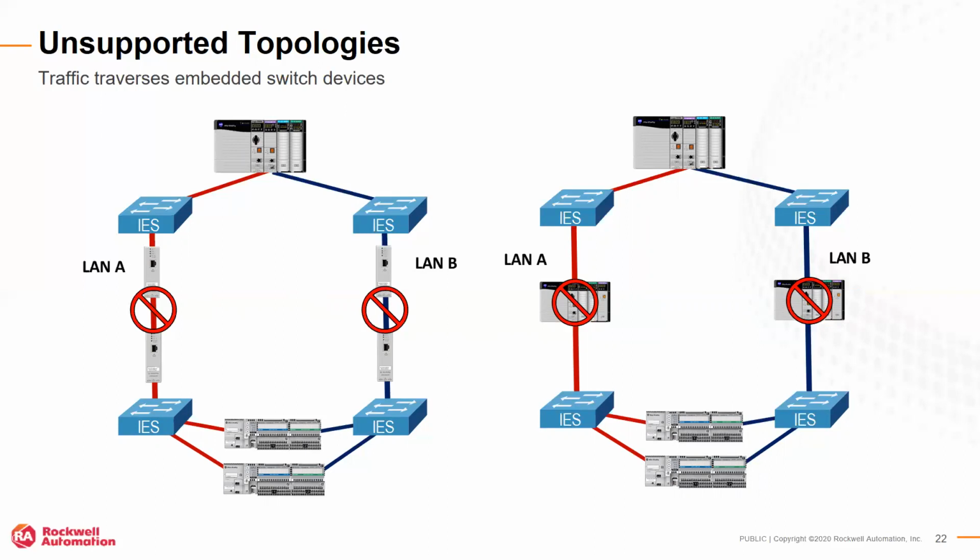One of the main reasons for this, as Mike also mentioned earlier, is that PRP communicates using larger communication packets that ETAPs and network bridging just don't handle well. But the industrial Ethernet switches, the 5700s and 5400s, do handle those better. That's why we recommend using fully managed switches and not smaller things like ETAPs or ControlLogix chassis.